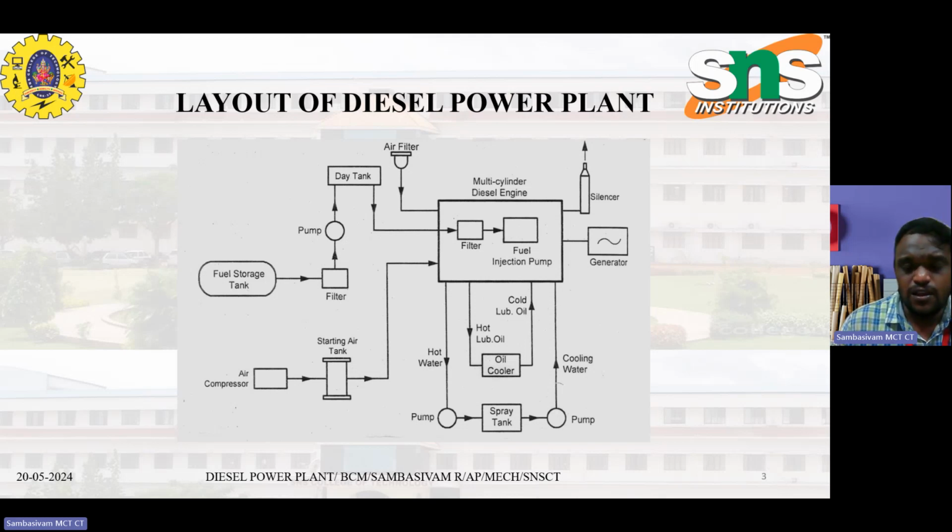Then it is fed into a boiler. We also bring purified water from rivers and other sources, which is clean, and send it into the boiler drum. When the fuel is burned, a lot of heat is generated, and the thermal energy is given to the water, which converts it into steam. This steam is under high pressure and is then passed through a superheater and then to the turbine. The thermal energy of the steam is converted into mechanical energy through the turbine.